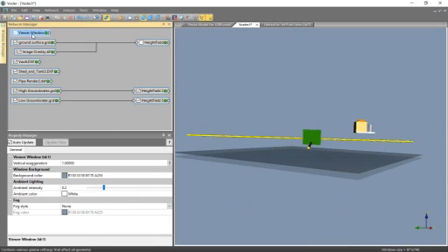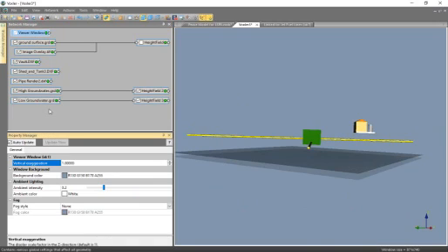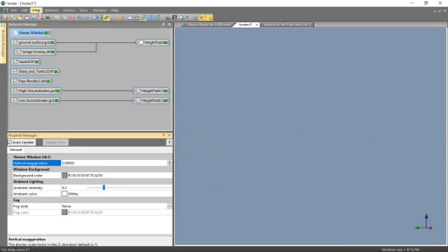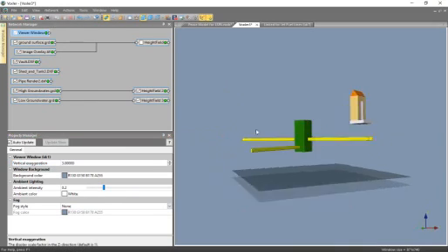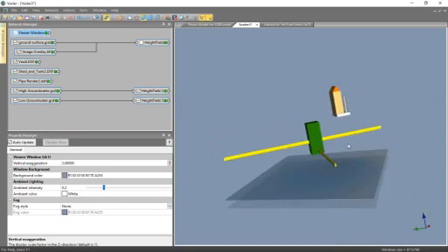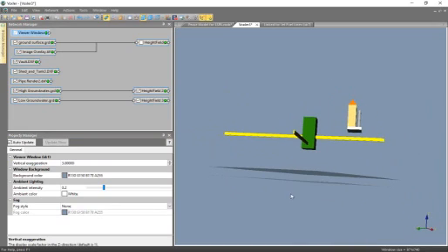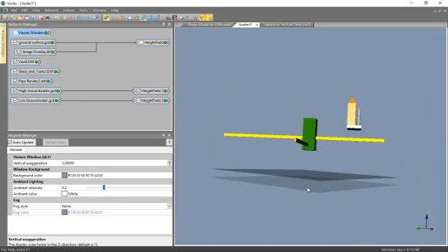So we can account for this really quick and easily by adding some vertical exaggeration. So I've clicked the viewer window module up in the network manager, and I'm going to go down to the property manager and give it 3 times vertical exaggeration. Let's fit that back to the window. And yeah, you can see that there's some stretching going on here, but we still get a good idea of what's going on. And more importantly, we can see a little bit of space here between the high and low groundwater grids or surfaces.